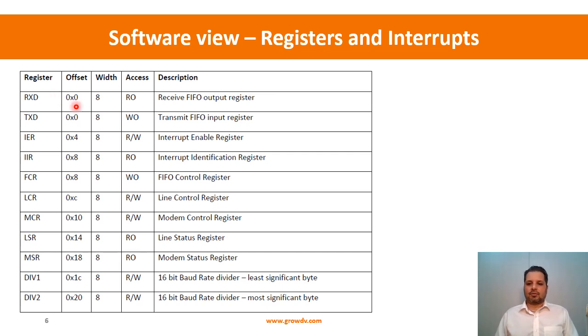But when the processor issues it, it will issue it to 0xFF00, and then your APB bridge will capture that address, and it will have its own mapping mechanisms through which it will figure out that this belongs to UART, and then it will extract the offset and play it out on the APB bus. That's one of the ways to implement it, and that is what we will stick to in this particular example. Depending on the SOC, there could be different ways people could map, whereas the decoding itself could be done by the slave.